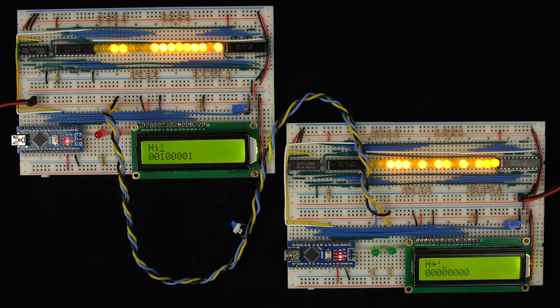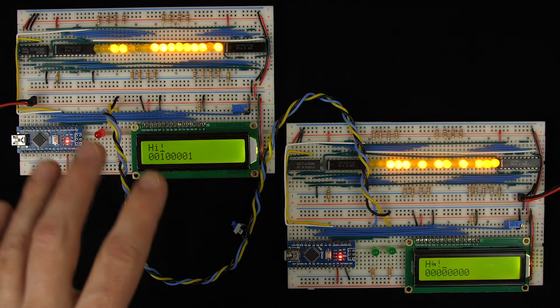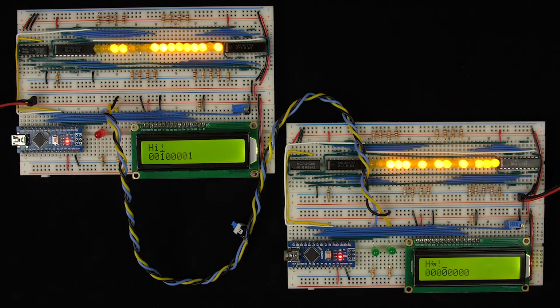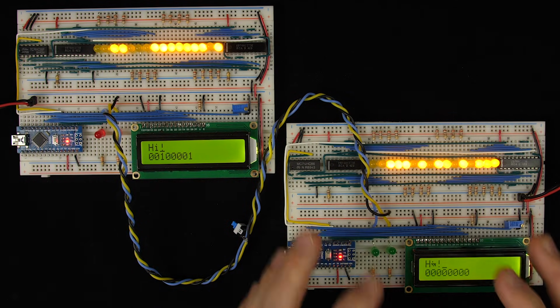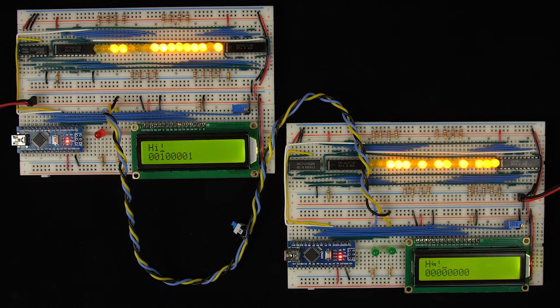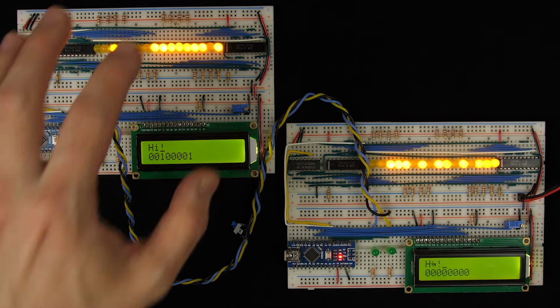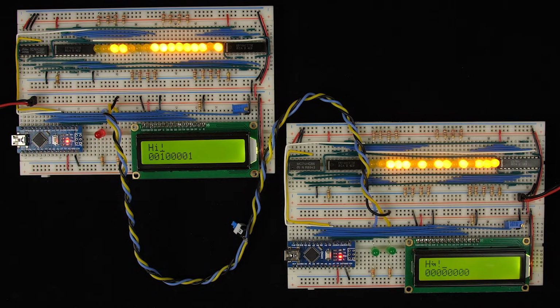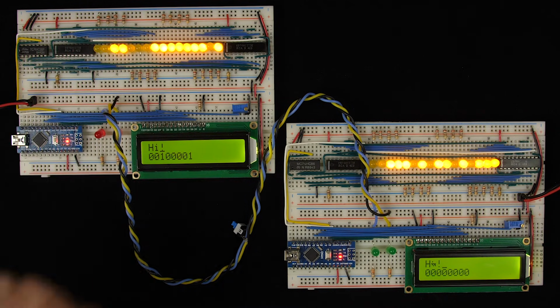But of course, in reality, that's not how a CRC check works. You don't just compute the CRC on the transmitter, compute the CRC on the receiver, and look at both. Because how does the receiver look at the CRC on the transmitter? The receiver is the thing that's validating the message, and all it has is the CRC that it's computed. So it has no way of knowing that it's different. So what we need to do is transmit the CRC that's computed on the transmitter to the receiver so that the receiver can do that comparison, if you will. And so we actually have to make a few changes here on the transmitter in order to do that.